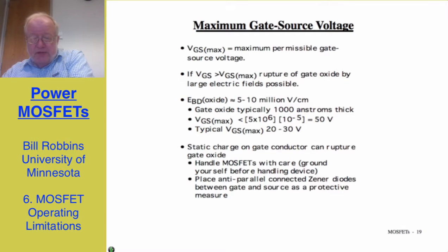So when you're handling MOSFETs, make sure that you are well grounded so that you don't put static charge on the gate just by careless handling and destroying the device. I could tell you stories of how I have in past years been demonstrating MOSFET circuits to undergraduate laboratory classes, and I have ruptured the gate oxide and ruined the devices.